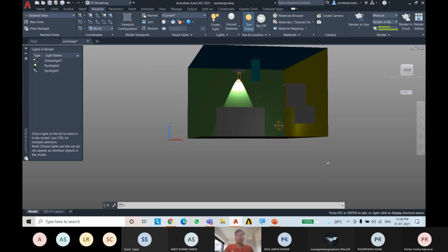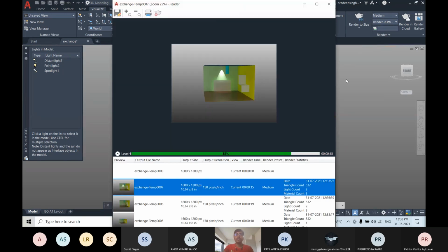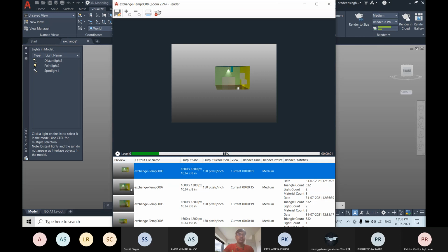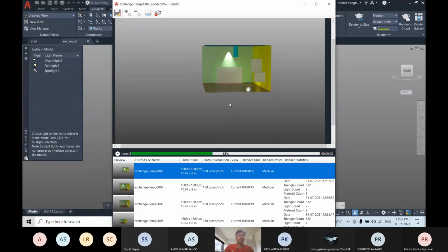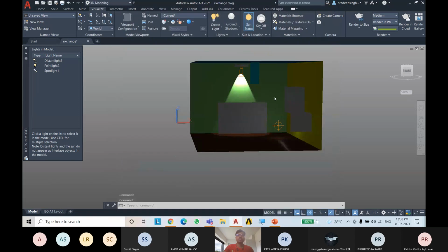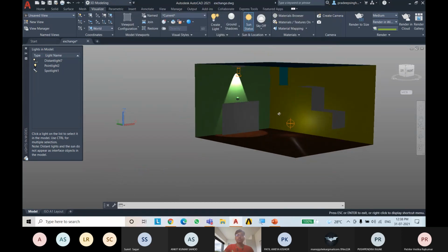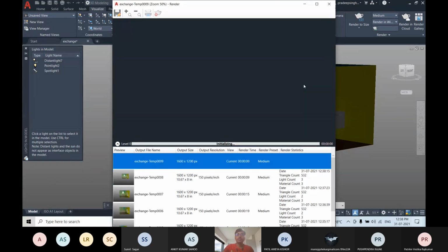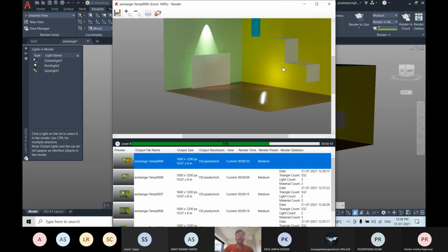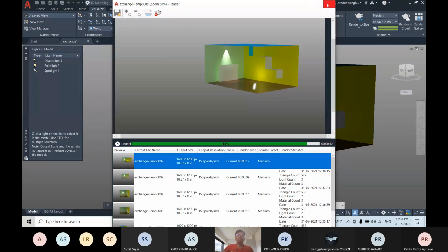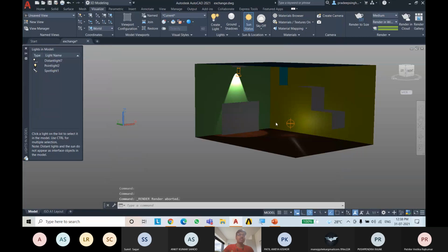So now you can again render it, then see the changes. Just change the angle of rendering now. Now render it. You can see that because of this spotlight, some light has come there, and you can see that this also is highlighted. Now you can see that this spotlight has also come there.